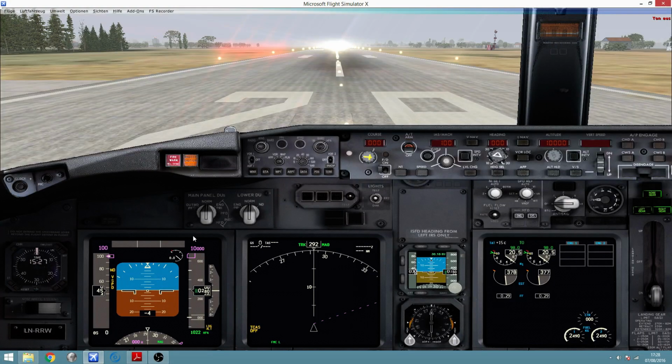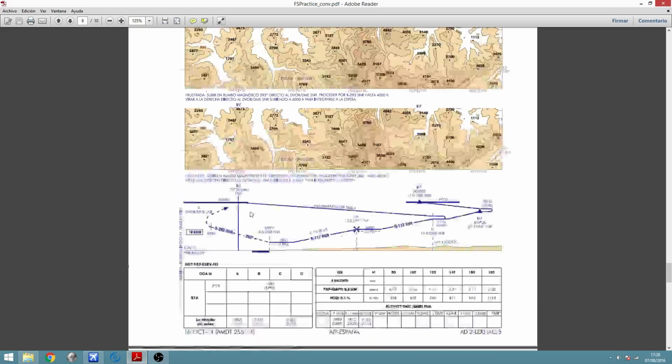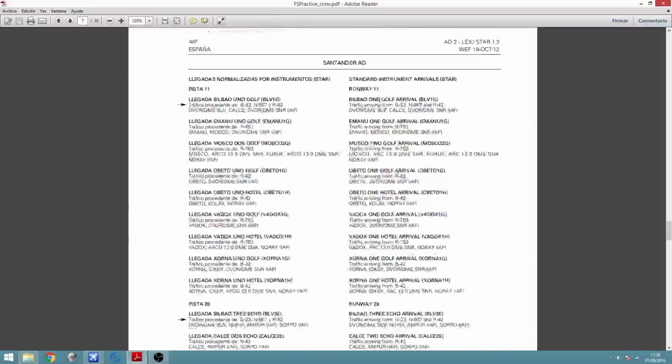And then I'm asking you to compute the deviation of the standard atmosphere in Celsius degrees. Assume that we are at sea level, so we were supposed to be here at 15 Celsius degrees, and the METAR, I think, said we were at 24 Celsius degrees. So the ISA deviation today here in Santander is +9. The transition altitude is determined in the standard departure chart.